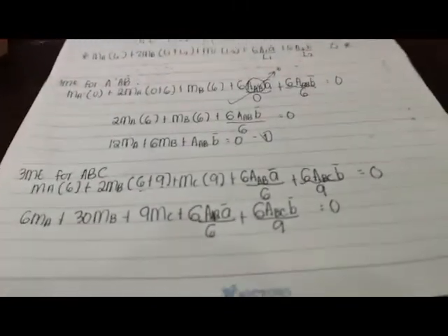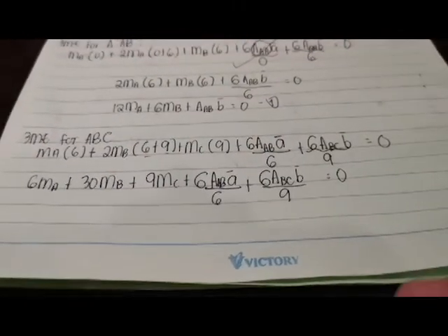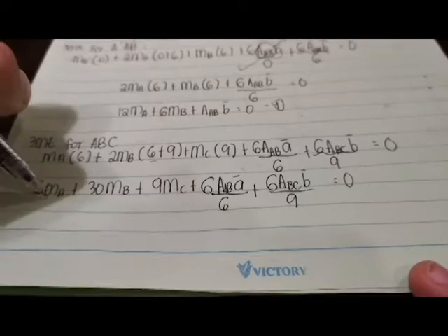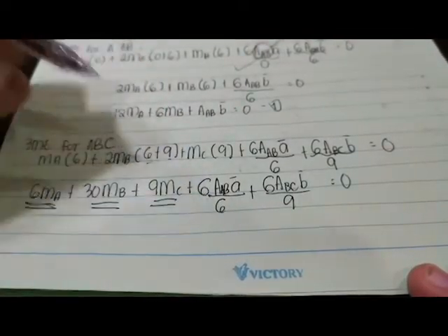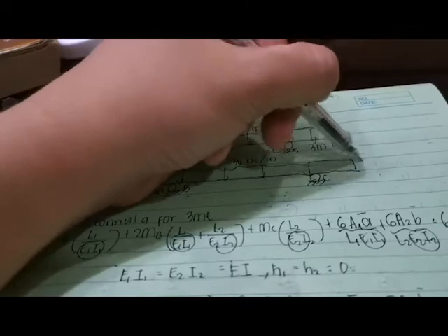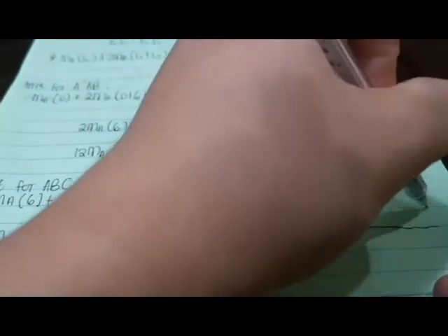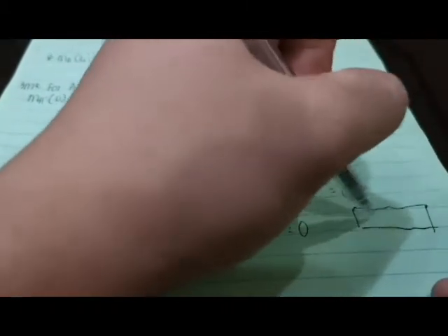So next, we found out that we have three unknowns. But wait, there's more. You have to remember that at point C we have an overhang. So therefore we can just isolate your span AC going to D. This is assumed to be 3 meters.